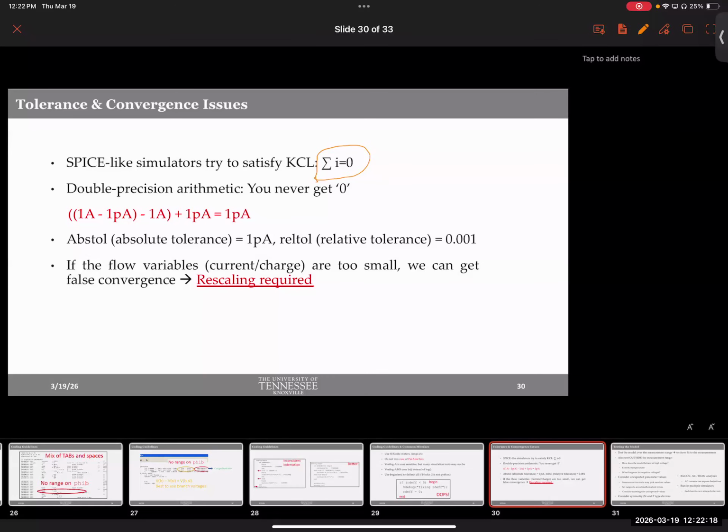Okay. Now notice, because of precision, see this line here. If you just manually calculate, you have 1 ampere, negative 1 ampere, they will be cancelled out. 1 picoamp, negative 1 picoamp, they will be cancelled out. But in your model, you are calculating step by step. You do one step, and then a second step, then a third step. You have multiple current contributions. I gave you an example which is completely relevant to this. I personally encountered it. For low voltage levels, thermionic injection or Schottky current was super low, like picoamps, and the others are like microamps. So compared to one, the other becomes negligible if it is not properly handled.